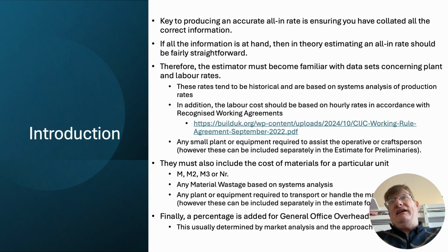Fundamentally, it's about having some historical figures on time and motion. Obviously, the more up to date, the better, because as the years have progressed, time and motion studies, or systems analysis if you want a posher, more modern word, show that we are much more productive now. So where a couple of years ago it would have taken, I don't know, 30 minutes to lay a metre squared of bricks, sorry, not 30 minutes, 2 hours, it now takes about 1.5 hours. Those are the sorts of things you're looking at.